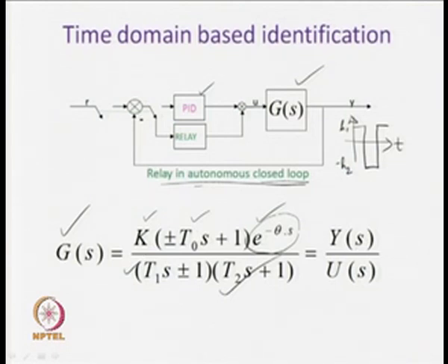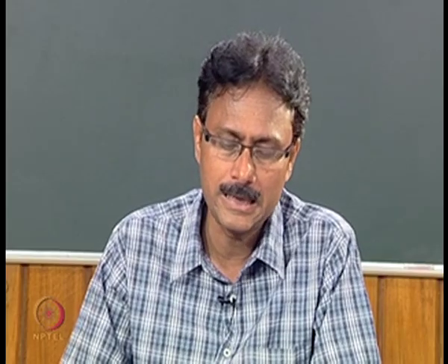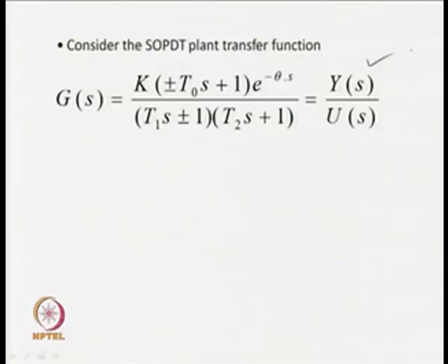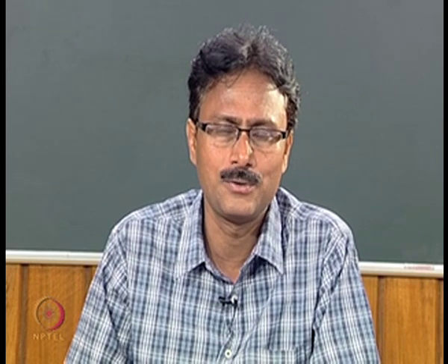Now, the output and input of the system are assumed to be, in the Laplace form, Y(s) and U(s). The system output in the Laplace domain is denoted by Y(s) and the input by U(s). When this transfer function is written in this form, further analysis can yield the representation of the transfer function in different time domain forms. We can have at least 3 types of representation of the transfer function model in time domain, and those are known as controllable canonical form, observable canonical form and diagonal form. Out of the three forms, it is often found that the diagonal form of representation of the dynamics of a system is convenient to handle. Therefore, we shall attempt to obtain the transfer function in diagonal state space equation form.